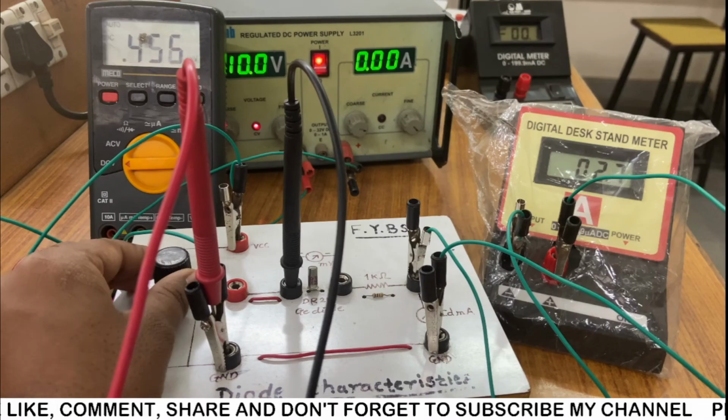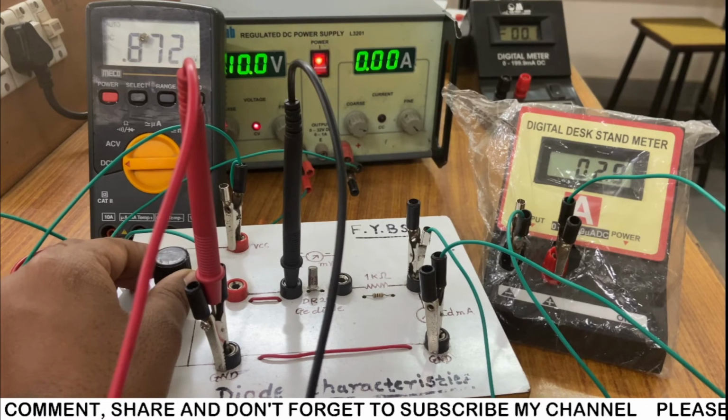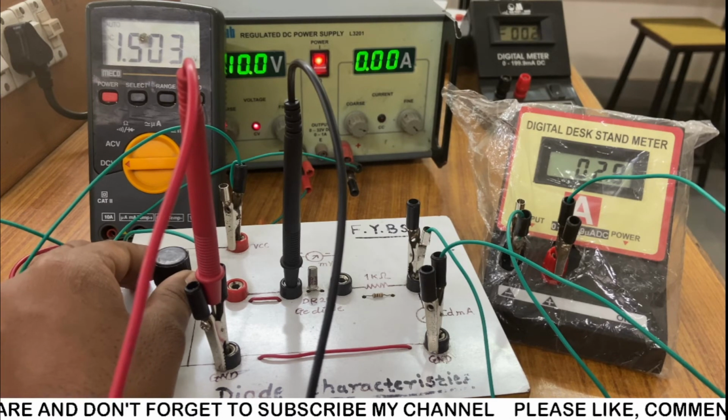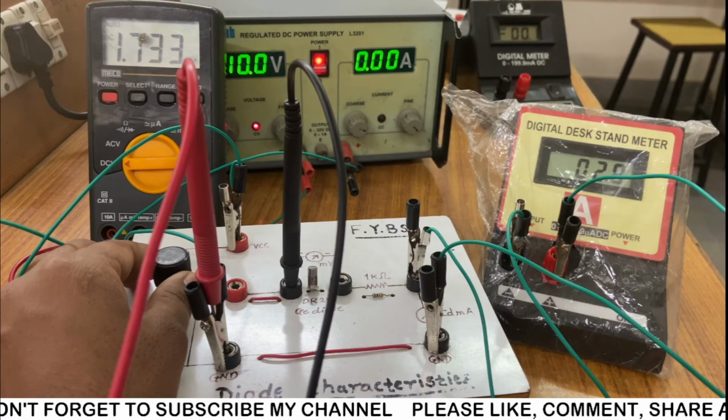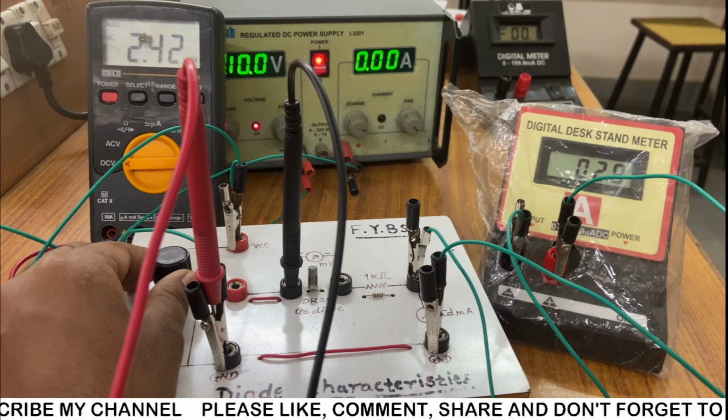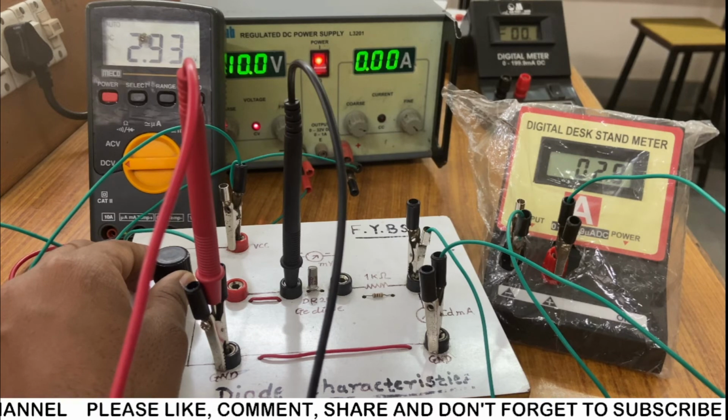So let's look at how in the lab we can do this experiment. The reverse bias connection is made and I am going to vary the voltage. I set it to 1 volt and the reading is 2.8. For 2 volt, 2.8. Going to vary the voltage to 3, 2.8, same reading.